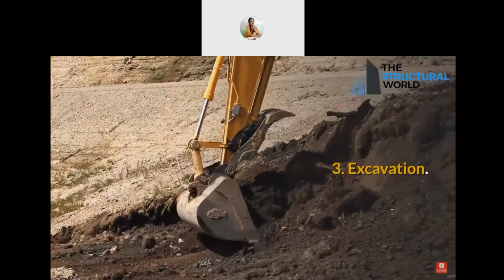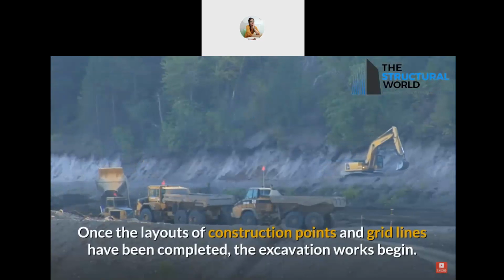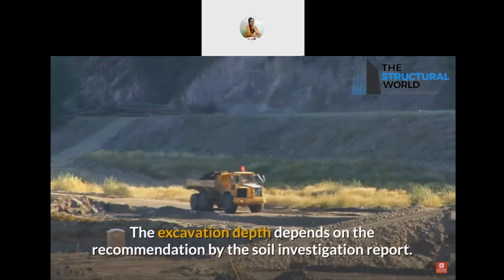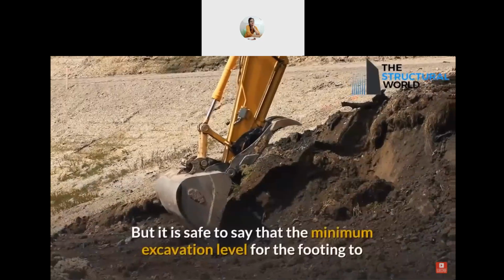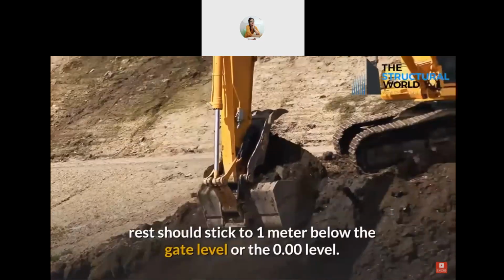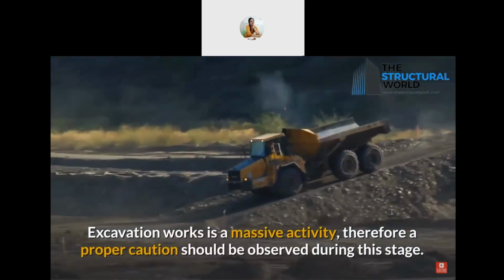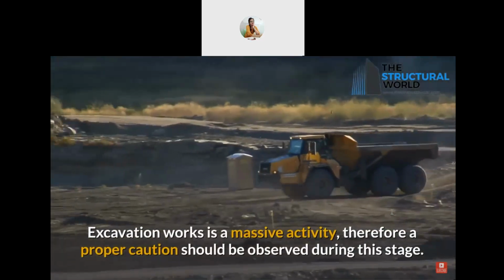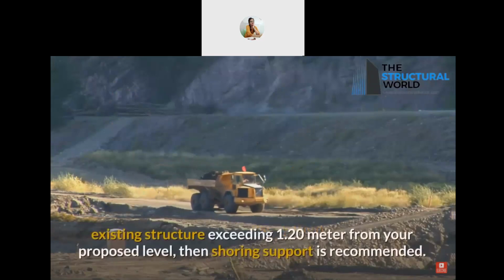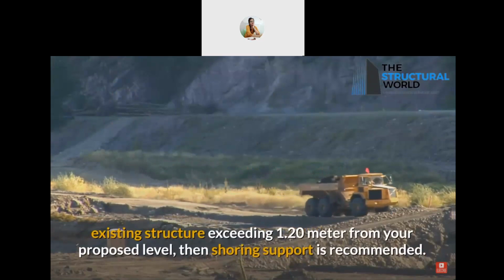3. Excavation. Once the layouts of construction points and grid lines have been completed, the excavation works begin. The excavation depth depends on the recommendation of the Soil Investigation Report. But it is safe to say that the minimum excavation level for the footing to rest should be 1 meter below the gate level or the 0.00 level. Excavation work is a massive activity, therefore proper caution should be observed during this stage. In the event that the excavation needed is along a neighbor's existing structure, exceeding 1.20 meters from your proposed level, then shoring support is recommended.